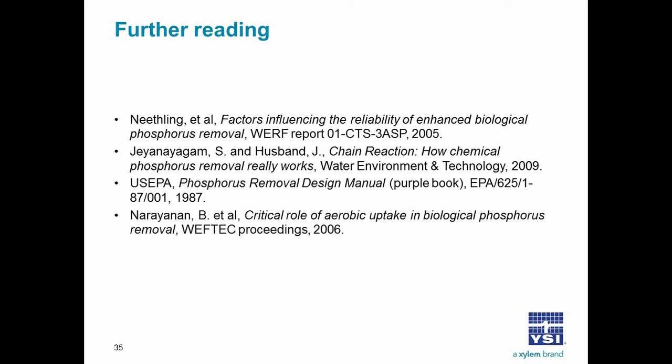Well, the answer is yes. But if you are doing biological P removal, it is very important to limit the chemical addition as much as possible. Because remember, these bacteria, these PAOs, rely on excess phosphorus in order to survive. And if you take away that phosphorus, it reduces their competitive advantage.